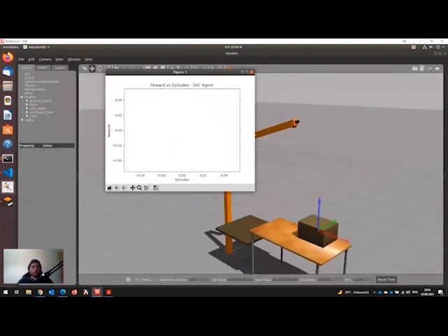So, I'm concluding now. It's possible to use an inverse kinematic approach to the reset mechanism, but there are a lot of constraints when taking this approach. For example, initially during the testing phase of the robot for the forward and inverse kinematics, there was a position error in the end effector frame due to the simulation-based joint controller.